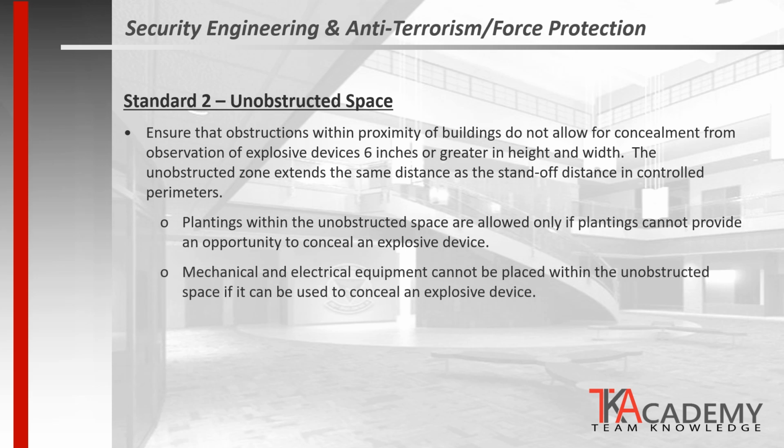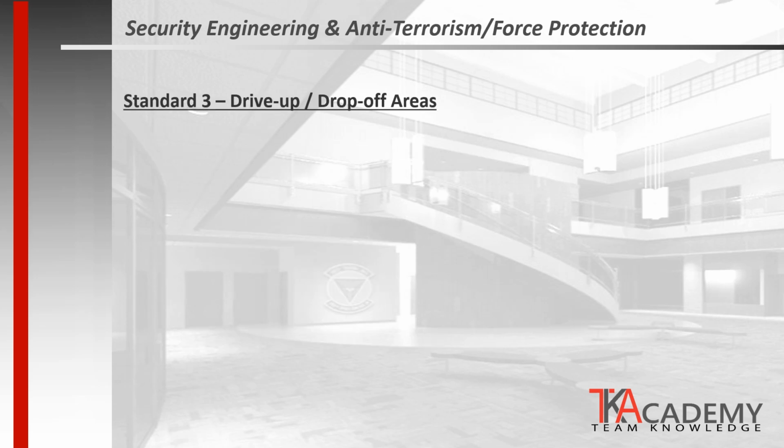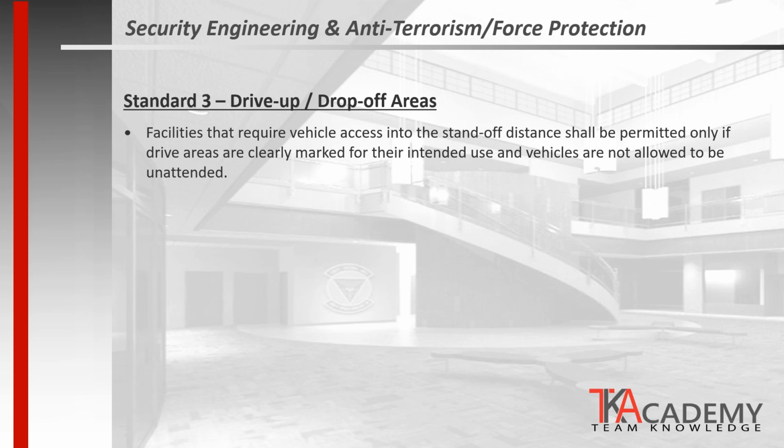Mechanical and electrical equipment cannot be placed within any unobstructed space if it can be used to conceal an explosive device. If a screen wall located within an unobstructed space is more than just a single wall, it must be enclosed on all 4 sides and on top. Standard 3 addresses vehicle drive-up and drop-off areas. Facilities that require vehicle access into the standoff zone, such as for loading docks, shall be permitted only if driving areas are clearly marked and vehicles are not allowed to be unattended.